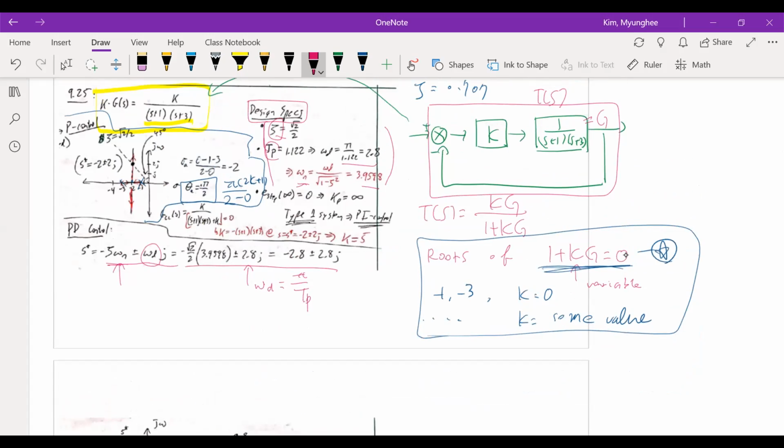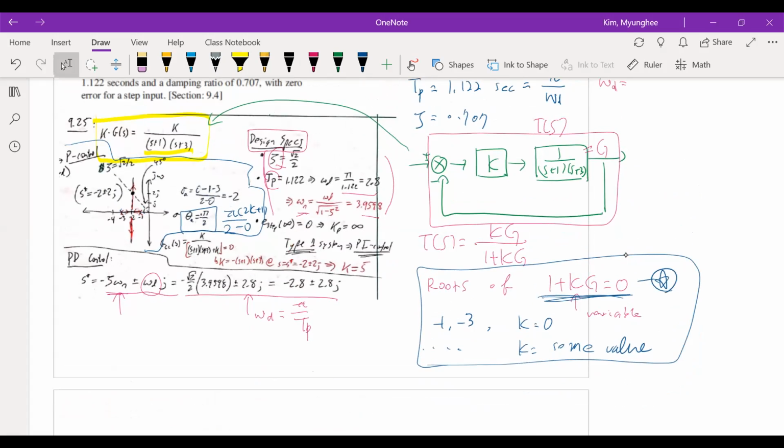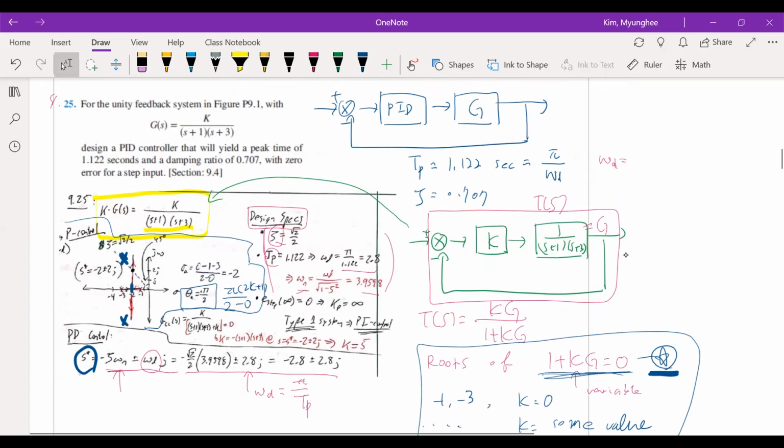And let's check that on the root locus. Here, let me use a little bit thicker pen. So this is the sigma A, and that point is near here. So it'll be about this position, which can't be a solution of this star equation because there's no such point on the locus. Whatever you vary in K, this desired pole location to meet the design spec can't be a solution of these characteristic equations. So what we need to do is design the controller.